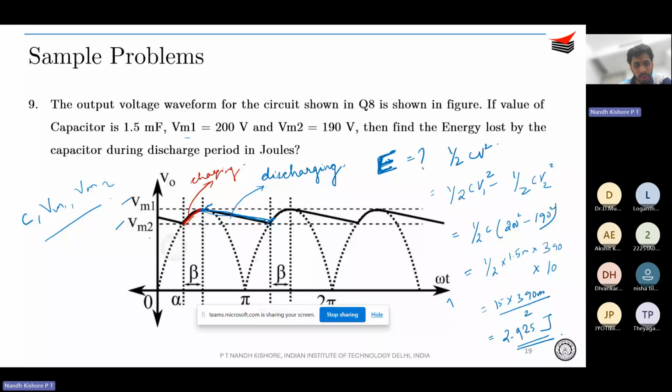The reason is, when your capacitor voltage is below your AC input voltage, obviously the capacitor will charge up, correct? And once your AC input voltage goes less than the capacitor voltage, the capacitor will slowly discharge into the load, until your AC input voltage becomes higher than your capacitor voltage.